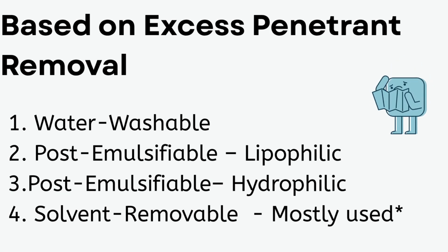1. Water washable. The extra penetrant can be easily washed off with water. 2. Post-emulsifiable, lipophilic. First, an oil-based emulsifier is applied, it mixes with the penetrant. Then it can be washed off with water. Used when better control and sensitivity are needed.